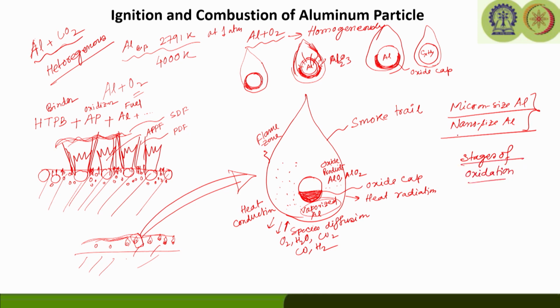Depending on how the heat transfer from the gas to the particle is taking place. Now, the heat and mass diffusion inside the particle is going to also happen, how the melting of the aluminum core is happening, how the phase transformation is happening in the oxide layer, how the oxide layer is going to crack and leading the oxidizer to react with the molten aluminum. So, that all is actually influencing the mechanism, how the mass diffusion across the oxide layer is taking place, how the heterogeneous chemical reactions like aluminum with oxygen are going to take place. All is going to influence the burning of aluminum particles.